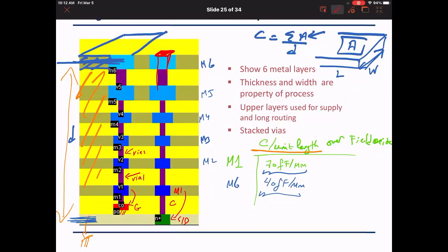What's the difference between a via and a contact in this context? A via is between metal and metal. A contact is between metal and source/drain, or metal and poly or gate. The difference in terms of fabrication is nothing, but we use the names to differentiate, because the rules on them are different: it has to be designed more carefully because it's at the smallest layer, so we call it a contact.